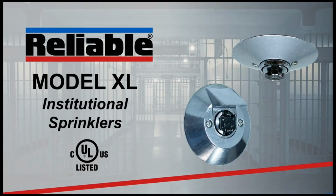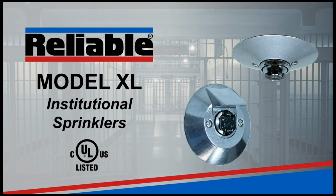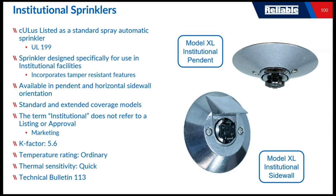All right, so next up, institutional sprinklers. We have the Reliable Model XL institutional sprinkler, UL listed as a standard spray sprinkler under UL 199. Institutional sprinklers are another version of a special sprinkler that really is about marketing. There's no listing or approval that will validate the tamper-resistant features that are found in this type of product.